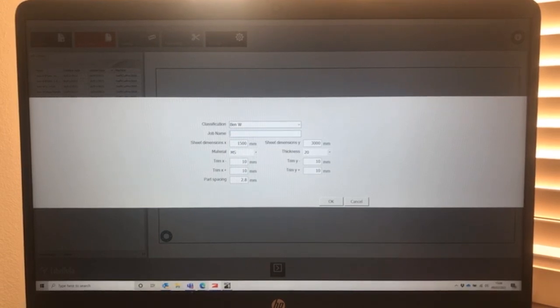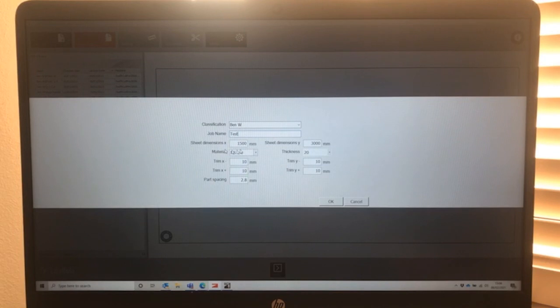The next section is the sheet dimensions. At this point you get the opportunity to put in the size of the material that you're going to be working on. In here we've got this set to 3 meters by 1500. If you've got offcuts or different sizes of material, all the way through to, say, only a meter square, when you're coming to do a nesting, it's going to form an integral part of that. So you put in the associated sizes that you've got to allow the nesting aspect of this to take place.